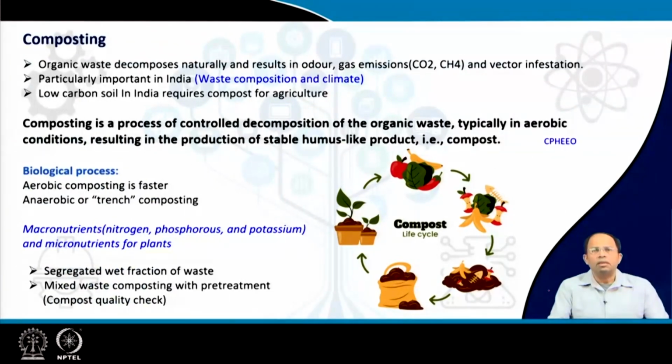So, composting is the process. It's a controlled process, of course, but as you know, organic waste decomposes naturally, and this results in different kinds of gas emissions such as carbon dioxide and methane, and sometimes in bad odor. If the composting happens in anaerobic conditions, then it will result in bad odor as well. And whenever certain materials decompose, you will see some amount of vector infestation as well. So that's the natural process. Every organic matter decomposes, and composting actually utilizes this decomposition process.